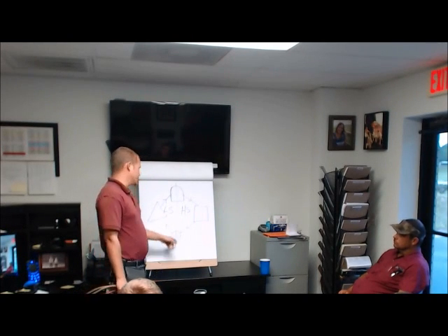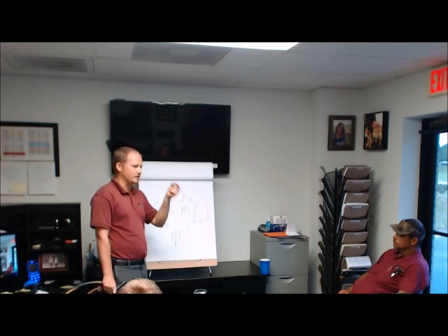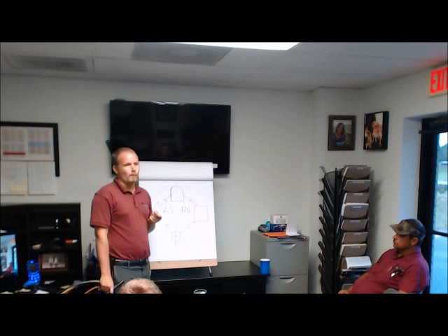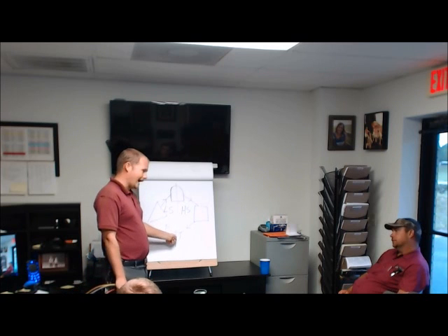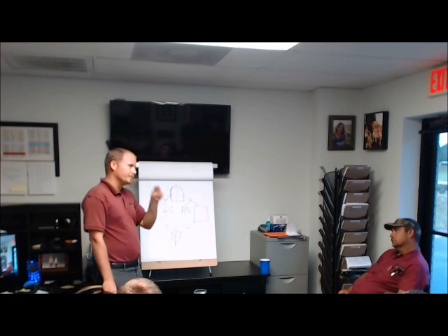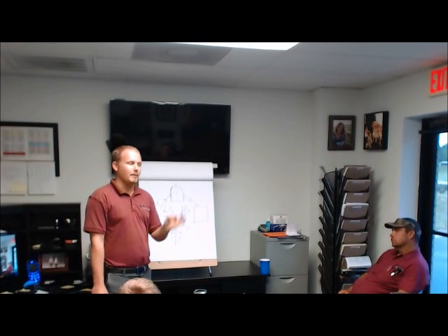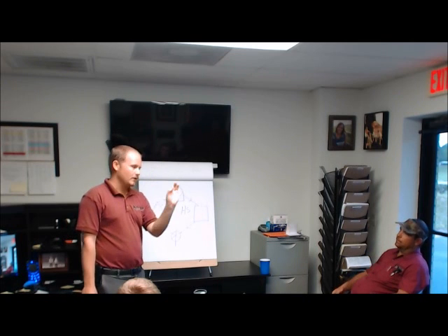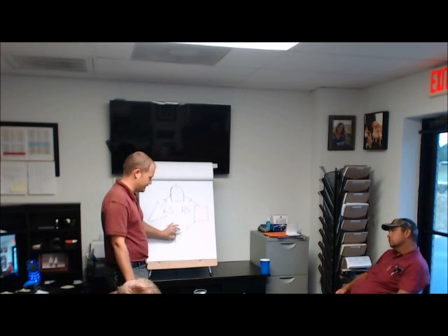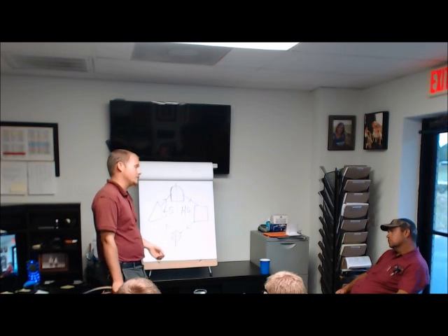That's where your pressure difference takes place. If you guys have ever seen a system, where is the point at which you start to see temperature change from warm to cold? Right after the metering device. Directly after the metering device, but even more so than that, because we tend to think of an expansion valve as a whole part. We always like to think of things as entire parts, but it's the exact point at which the pressure drop occurs that you see the difference. So it'd be an orifice. Right where that orifice is, right where it goes from big to small, right where it restricts, that's where the pressure drop occurs, and that's where you see the difference in pressure.